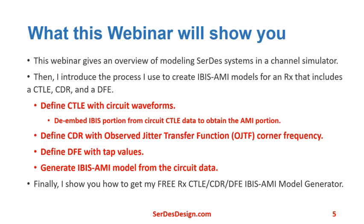What this webinar will show you. This webinar first gives an overview of modeling SerDes systems in a channel simulator. Then I introduce the process I use to create IBIS-AMI models for a receiver with a CTLE, a CDR, and a DFE. Define the CTLE with circuit waveforms. Define the CDR with its observed jitter transfer function, corner frequency. Define the DFE with its tap values.